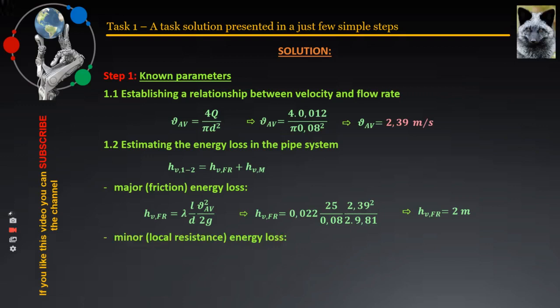And this can be done according to the equation presented in the slide. Once again, the parameters must be substituted with their numerical values, as I only find it necessary to discuss the calculation of the summarized coefficient of local resistances. For convenience, I suggest adding up all the individual local resistances coefficients, like shown, just look the ones colored in orange, remembering that their values are valid and applied for 1 unit.